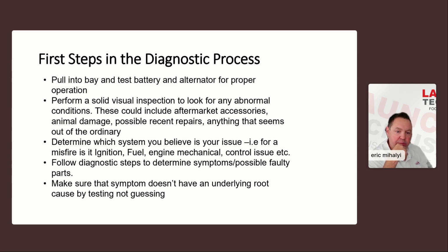If you know that there's been recent repairs, whether you talk to the customer or you look and see that anything seems to be out of the ordinary. I've worked on cars that have had all kinds of weird problems. Talk to them. I had a timing belt put on 3 months ago. And then what you find is that they didn't route the wiring harness back the exact way that it came. They kind of just did what they had to do.